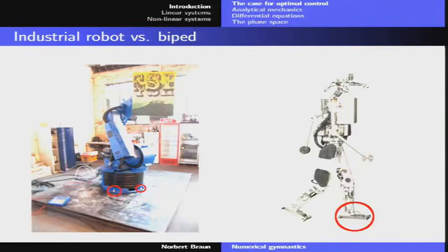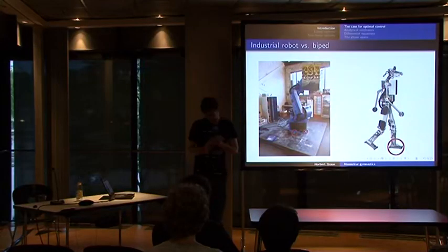And the bipedal robot doesn't have that luxury, because the leg that's on the ground is really only pushed to the ground, and it's not bolted to the ground. And so this bipedal robot really has to worry about not letting the reaction forces on the stance leg get too large. And this problem can't be solved by stronger motors alone. If I stand like this and then I try to put my body on this side, then I'm going to fall over, no matter how strong I am. So for more fancy robots, like this bipedal robot, the intrinsic dynamics really do matter.